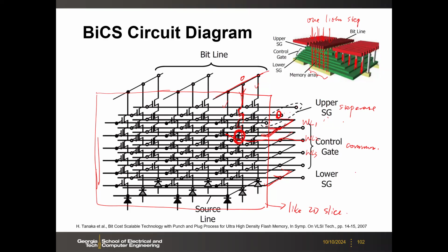So here, when you make the contact vias, you have to stop at different layers. Of course, the naive way is you do the lithography separately, but that will diminish all your benefits, right? You just want to do one shot litho, but if you separate this contact via fabrication into different litho steps, then what's the point of doing this 3D?